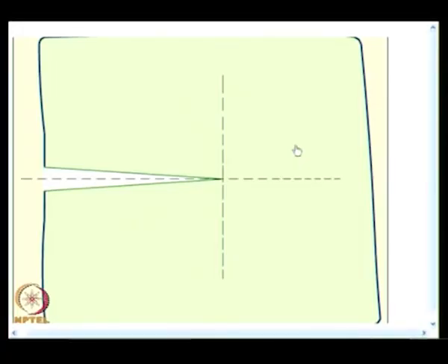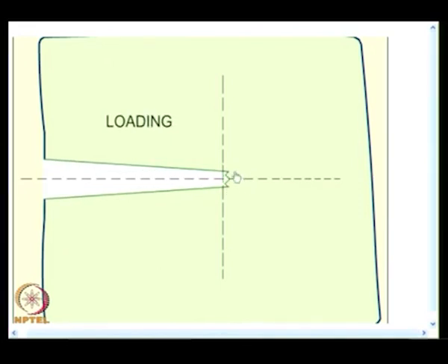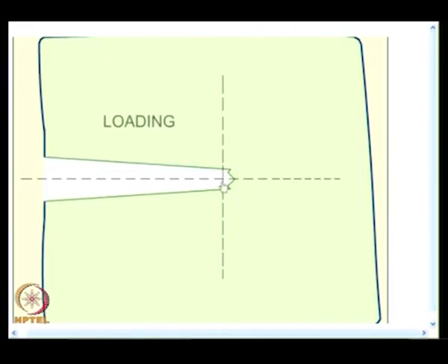Now, what I am going to draw your attention to is that the model says there is crack tip blunting, and then it becomes sharp when it is unloaded. The crack has grown by loading, it has become blunt, and when I do the unloading, it becomes sharp. Common sense tells this should leave some residue on the actual material, because you say that it is opening, closing, opening, closing, opening, closing, it becomes blunt and sharp, something should happen.